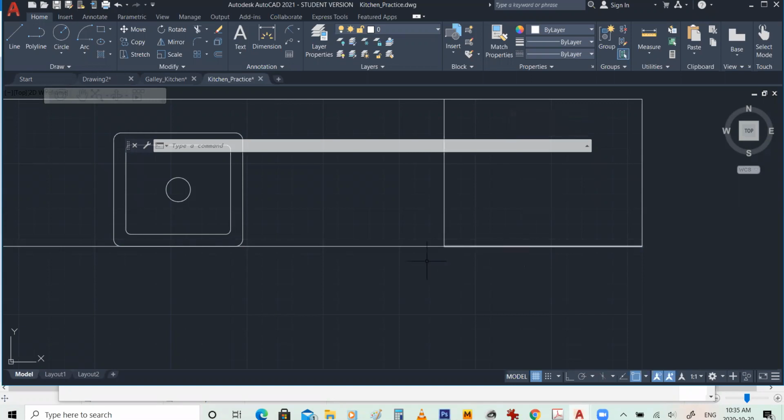now I'm going to hover over and find that the line has been divided into two segments. One of those segments is the segment that I wanted here. And this is by just making a selection of break at point. So make sure that you write it here, break at point, and select the line and then select the point where you want the line to break.